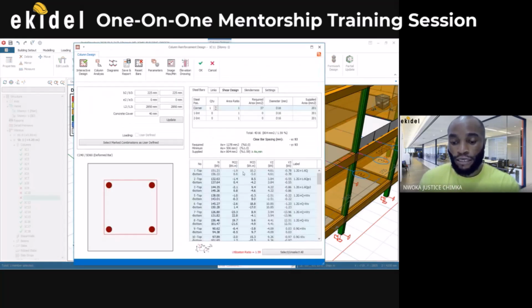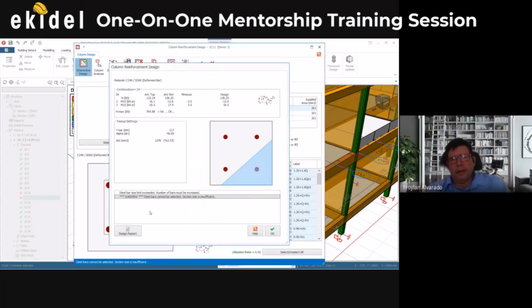Now you can see that it is failing based on the U ratio, because the section is small. U ratio is above 1. Can you see that here? It's more than 1. So right now I need to increase the section of the column, because even if we design again, it's failing by almost 40%.